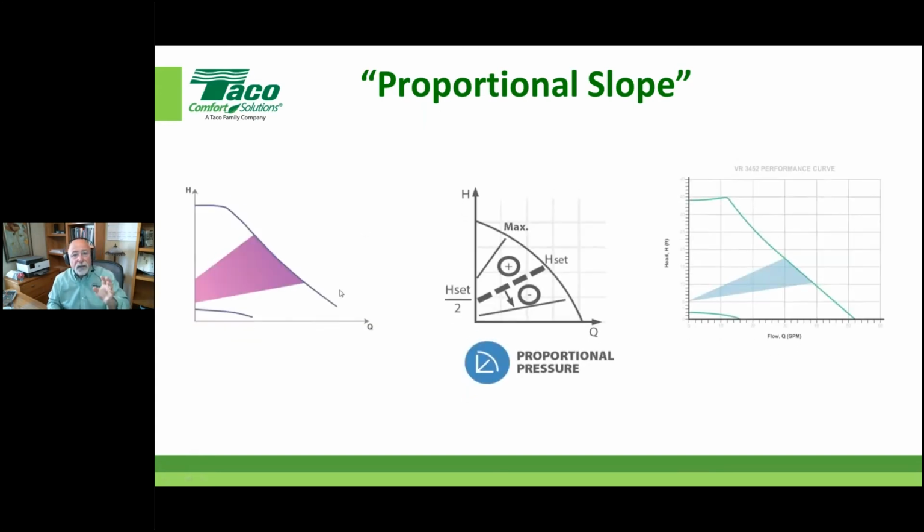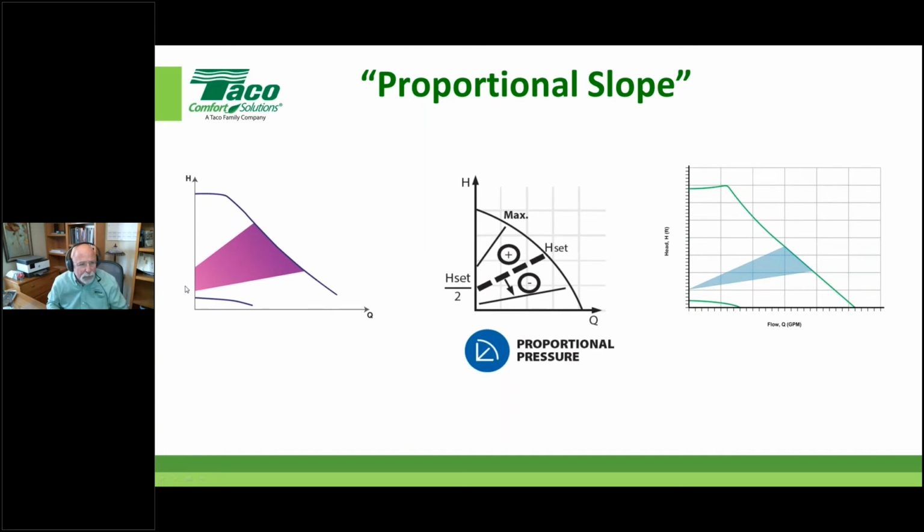So anyway, this is what I was talking about earlier. If you look at the left side of these pitches, and they could be anybody's, I'm showing you several here, if these wedges are nice and fat in the back, then they are most likely a fixed pitch. The pitch is actually around 50%, and I showed you that one at 58. Generally speaking, around 50% is what most people have locked in on.